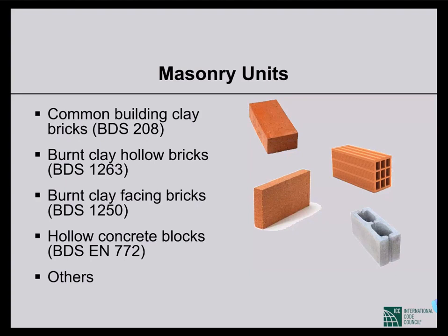These are facing bricks. Then, very important is the last type, hollow concrete blocks. Concrete blocks are quite useful for reinforced masonry. In Bangladesh, engineers are not always very interested in using concrete blocks because they think they have low strength compared to bricks.